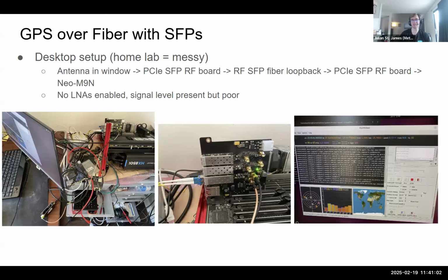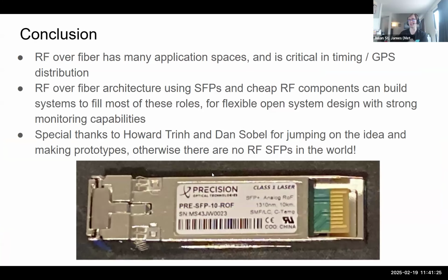Well, the board I built is just SMA and it goes directly into the SFP. If you build a different board, you would probably want to do it a little differently than what I'm doing here. There's a balun because the SFP is differential, but you have SMA single-ended, through some amplifier through a balun into the SFP. That's all I did. So the electronics is very simple.